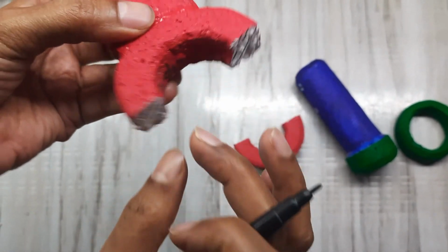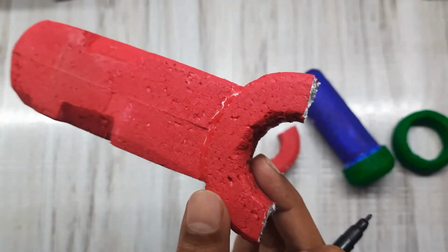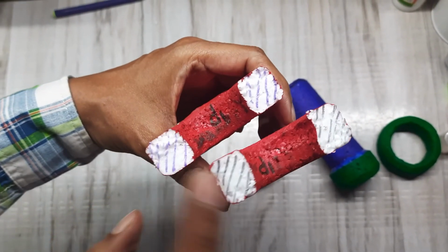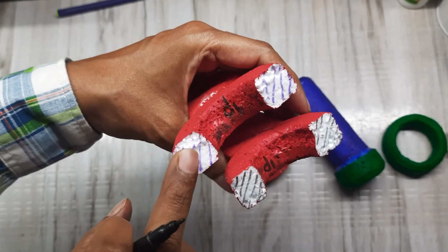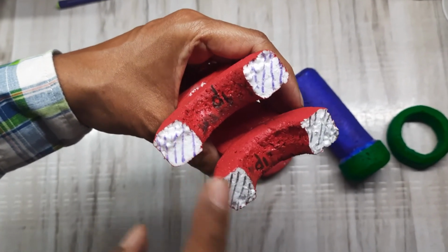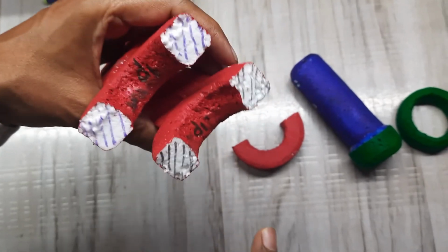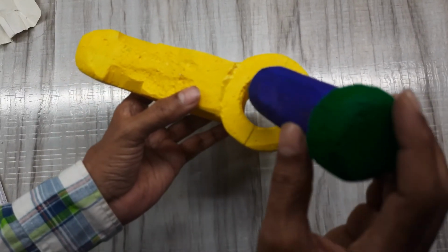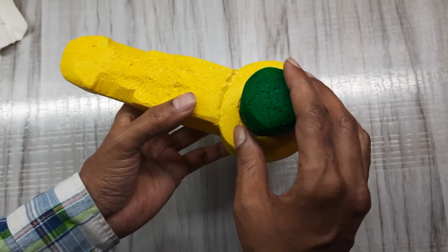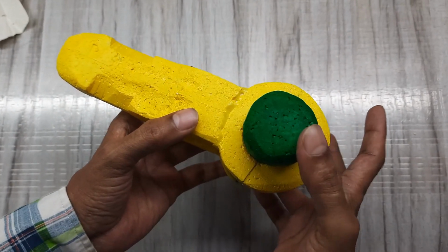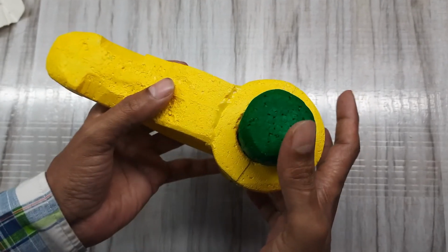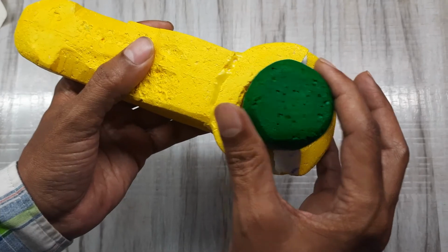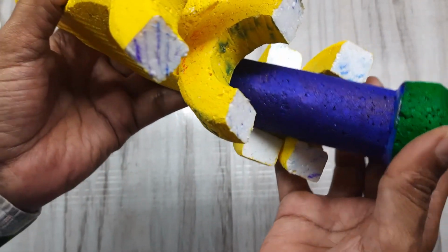D2 minus D1 into T means resisting area in the shearing and resisting area in crushing. In tension, both are same. Okay. Failure of double eye in shearing. Here also I am inserting a pin, right? Again it is a loose one, and same concept that when you pull it, now the shearing action will take place here like this.